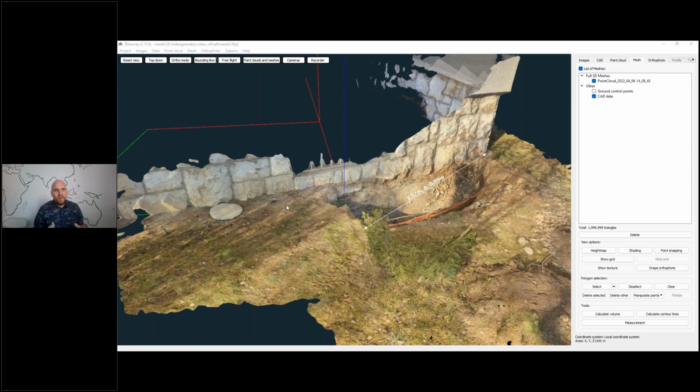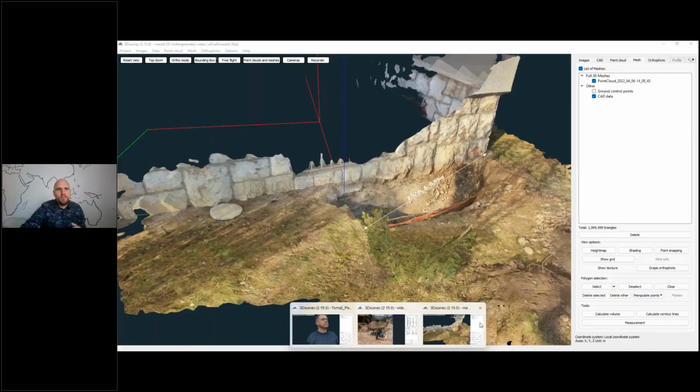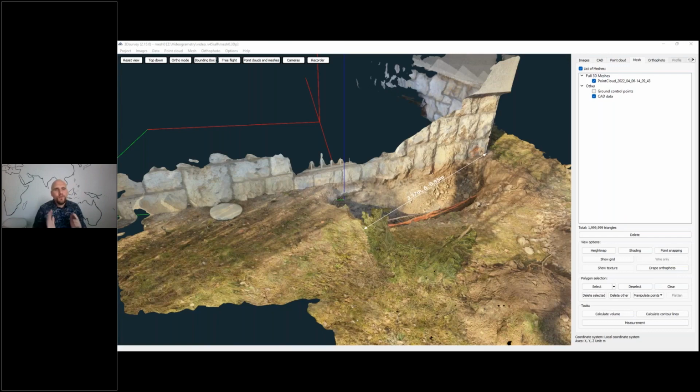With videogrammetry, what we get is a narrow strip when we are measuring. So if you wanted to measure maybe a 100 by 100 meter area, you would have to make very big videos, because one video frame will maybe cover 4 by 3 meters, while one drone image would cover 80 by 60 meters, for example. So it will depend on how you define very large areas, but if the area is truly large, I would use photogrammetry instead.